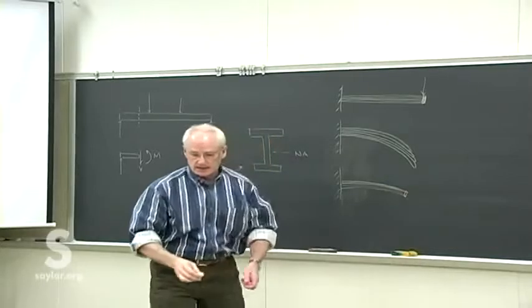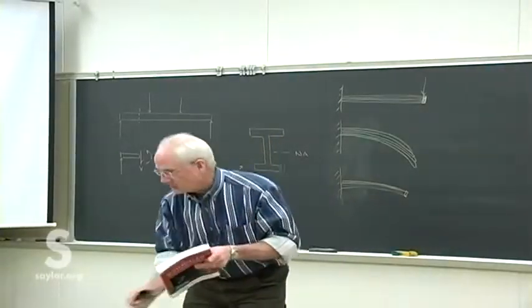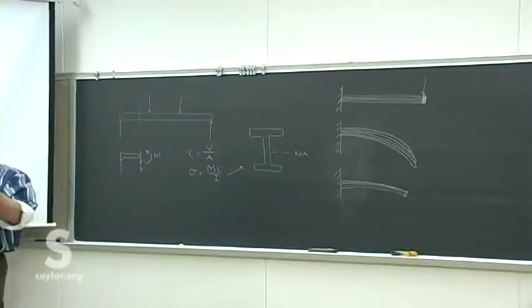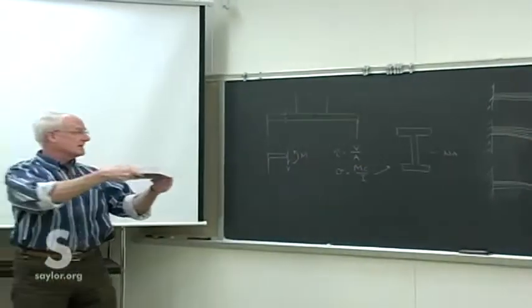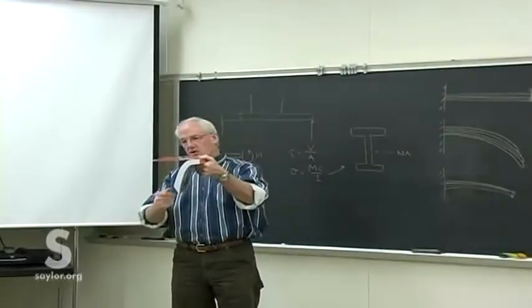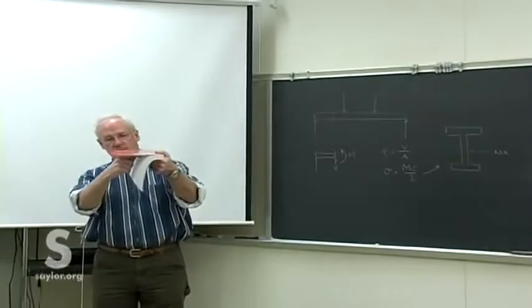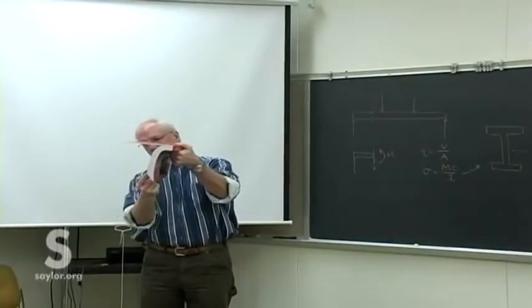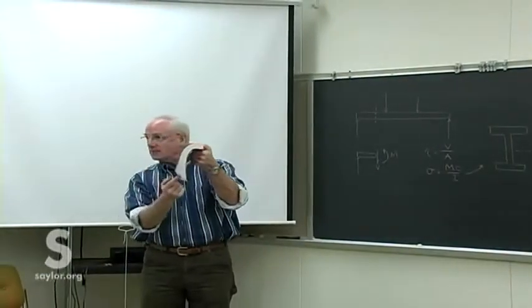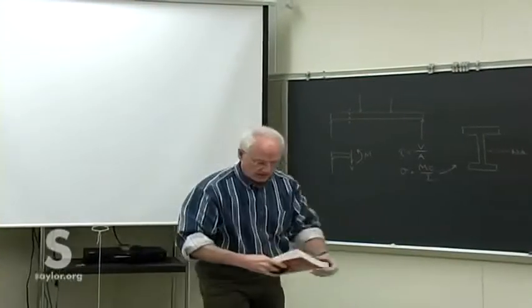And it's quite easily demonstrated with a simple textbook. If I let the sheets slide past each other, which is this kind of picture, then there's almost no resistance to bending. This is sticking up just because it's stiffer. But you can see if this was our beam and we allow the sheets to each slip past each other, it has almost no resistance to bending at all.